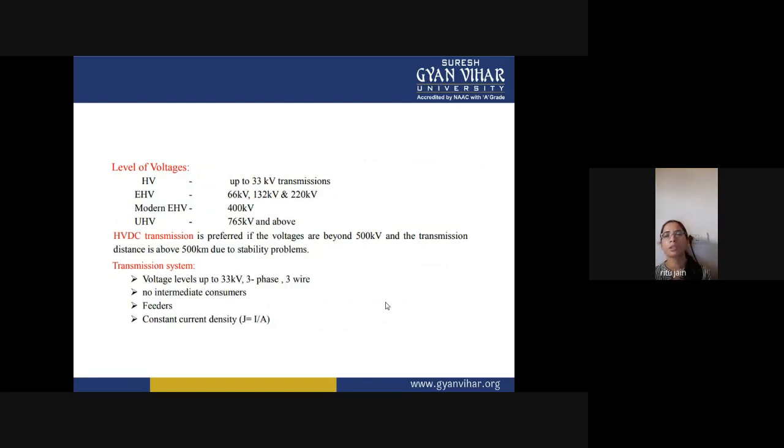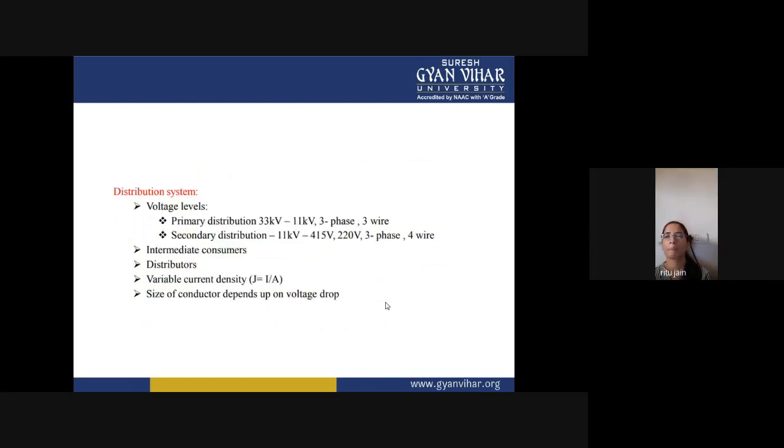So the transmission system has voltage levels up to 33 kilovolt, three phase and three wire, no intermediate consumers, feeder and constant current density, which is denoted by J is equal to I upon A, current upon area. Now let's come to the distribution system.